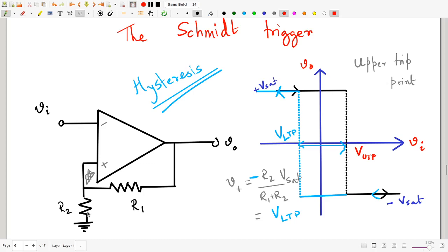So that is one application, protecting your comparator circuit from random noises so that your circuit actually responds only when the output exceeds the reference value by quite some amount, and then stays there once it has exceeded, even if random noise drives you below the reference voltage.